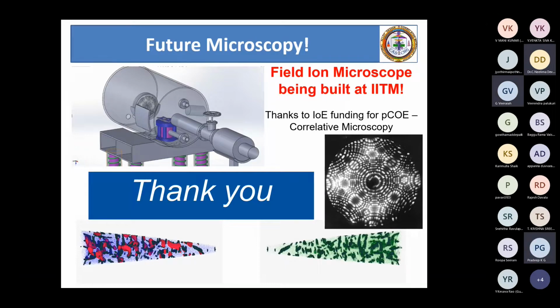At the same time, we do not want the MAX phase to be disordered. So if you want to do that, you need certain elements, for example silicon, to substitute aluminum when the aluminum comes out to react with oxygen. Therefore, we added silicon, which is a group element, with the hope that silicon will replace aluminum when the aluminum comes out for oxidation.